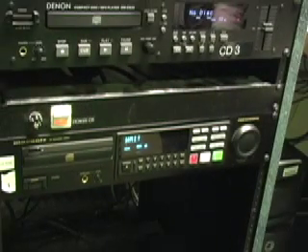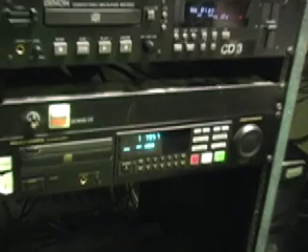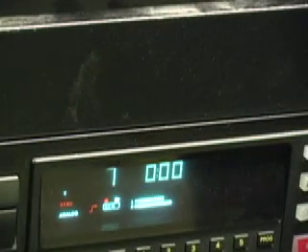The levels will start reading and you can adjust the record level/select knob to the left or right to lower or raise the input gain. This way you avoid distortion in your recording. The recorder will not begin recording until it hears a brief silence, approximately 2 seconds long. Then it will continue recording until stop is pressed.